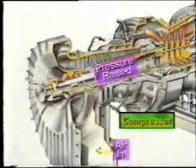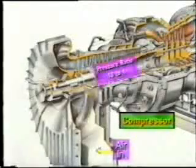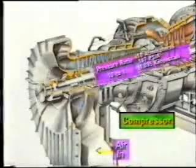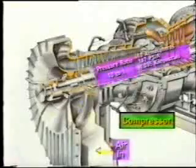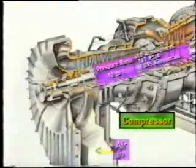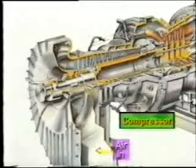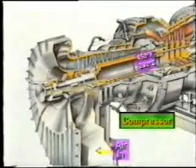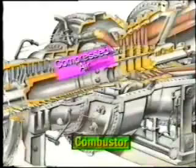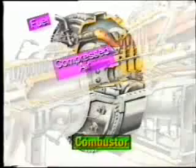The compression ratio depends upon the particular design of turbine. Where the pressure ratio is, say, 10:1, the pressure of the air as it leaves the compressor is 10 atmospheres. That is about 147 psia, 1,035 kilopascals, or 10.35 bar for you metric types. The temperature of the air will also rise as it is compressed, typically to about 450 degrees Fahrenheit, that is 230 degrees Celsius. The compressed air is routed into the combustion section, where it's mixed with incoming fuel.